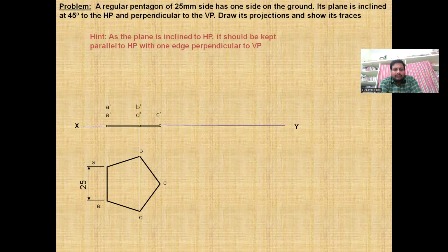Before that, we give the names to the front view. This line, we don't know the dimension of the line. Take the compass and measure the length of the line, and simply draw one line at 45 degrees. Then mark the measured length on that line. So we have taken the 45 degree angle, and the inclination of the plane will be there.